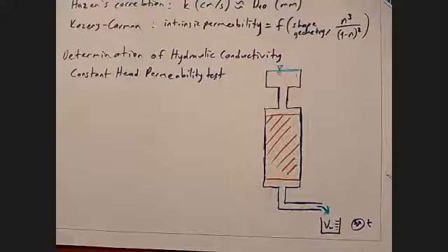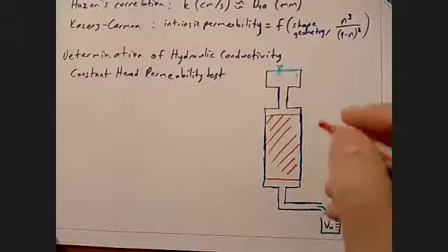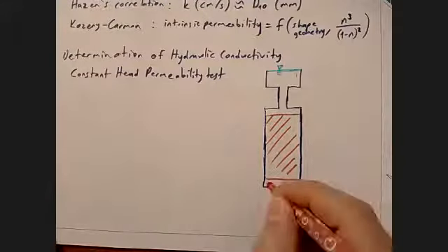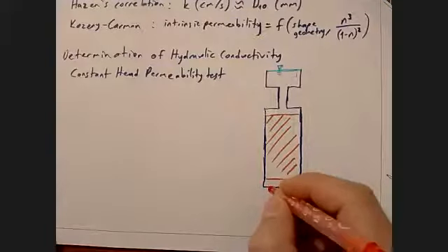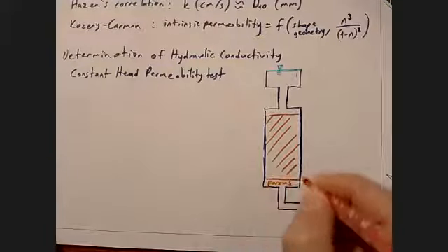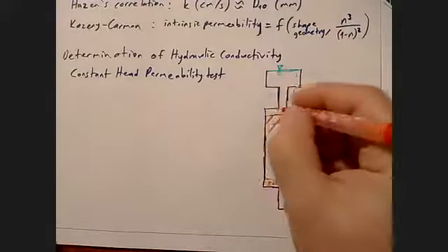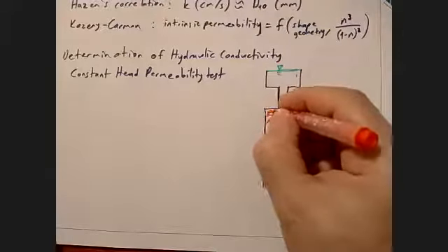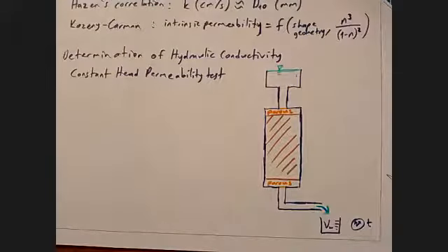So of course there are other little details you have here. For example, you have to put porous stones on top and bottom. Otherwise you can't keep your soil in place.